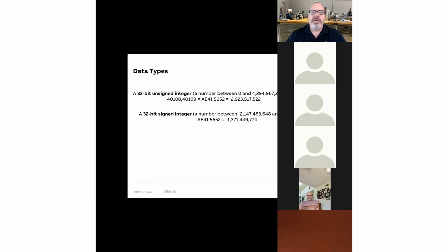And I bring that up because a lot of times what I'm seeing now, and it wasn't something that was done typically in custody transfer for flow computers, was that now we're asking for the total pulse counts coming off of flow computers, which is great. We want to see the total number of pulses that have been generated in that flow computer.